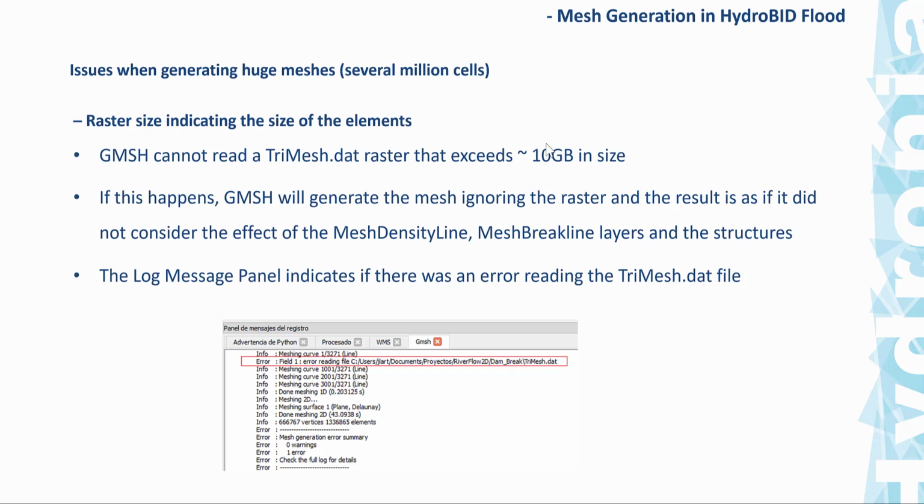So you would need to try to be in a range of number of cells that is less than maybe 10 million, or maybe 8 million. But in many projects, you don't need to go beyond a few 100,000. So we are talking about really big meshes here. Just so you have an idea, we have worked with people doing very large projects in Australia, who have been modeling the complete island of Tasmania, that has more than 300 watersheds, with a single mesh.